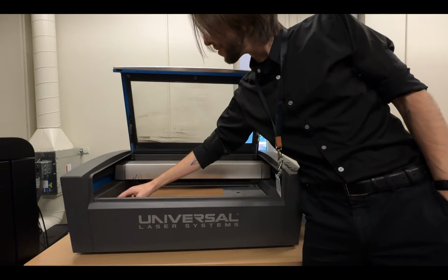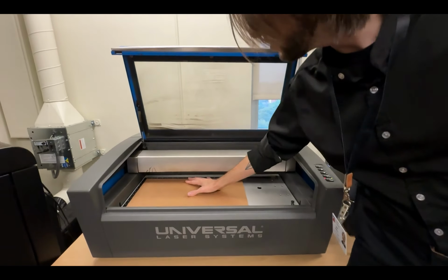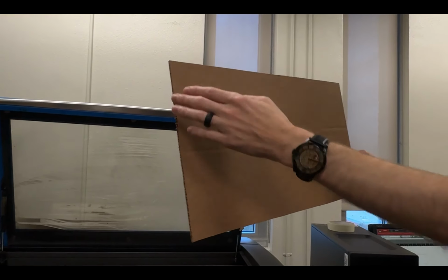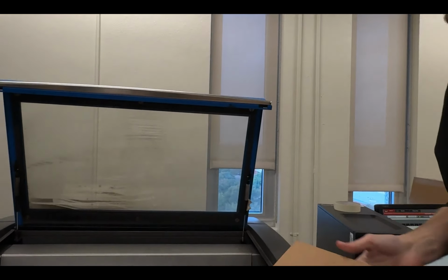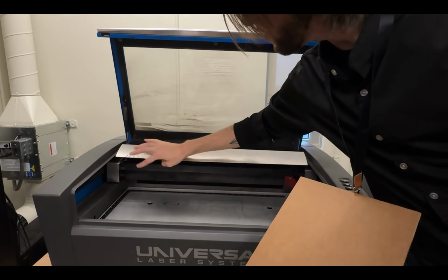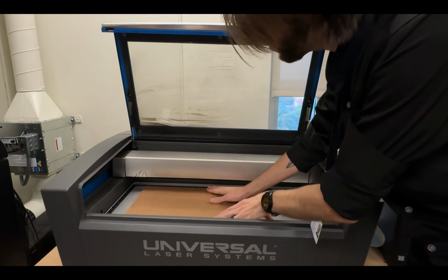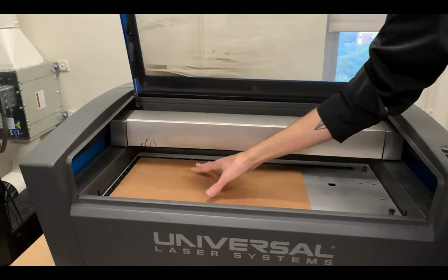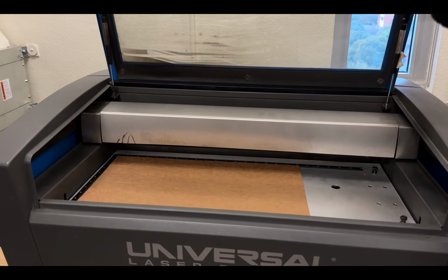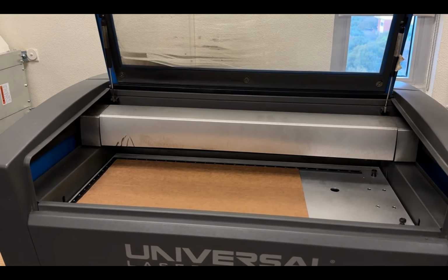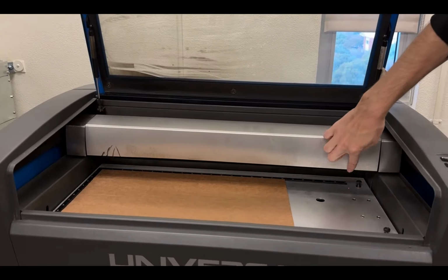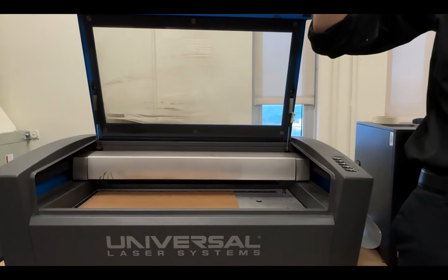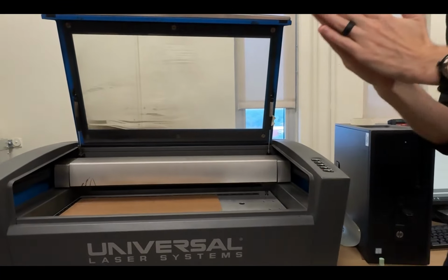So we'll line up our material, make sure that it is lined up to these two bars. That is definitely important. And to be honest, this is a pretty cattywampus piece. I'm going to try and use that 90-degree angle. This is also known as our 0,0 point, right? Which is in that top left corner, and you want to get it as far in there as possible and as flat as possible. If you have some sort of warped board, why does that not work? Right, that laser has to be exactly 2 inches, and if the board is warping even by millimeters, it's no longer 2 inches. Again, it almost works like a sword, right?